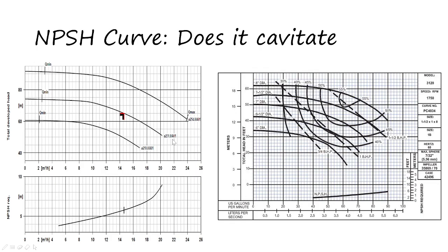So just to demonstrate how to check NPSH, these kinds of pump curves are there. You have an NPSH line over here. So, for example, if you have a 15 meter cube duty point, then this particular pump, which is not the selected pump by the way, will need an NPSH of around, say, 6 or 7 meter. So you have to track this flow value up to the curve and then go on the y-axis and check what is the NPSH required.